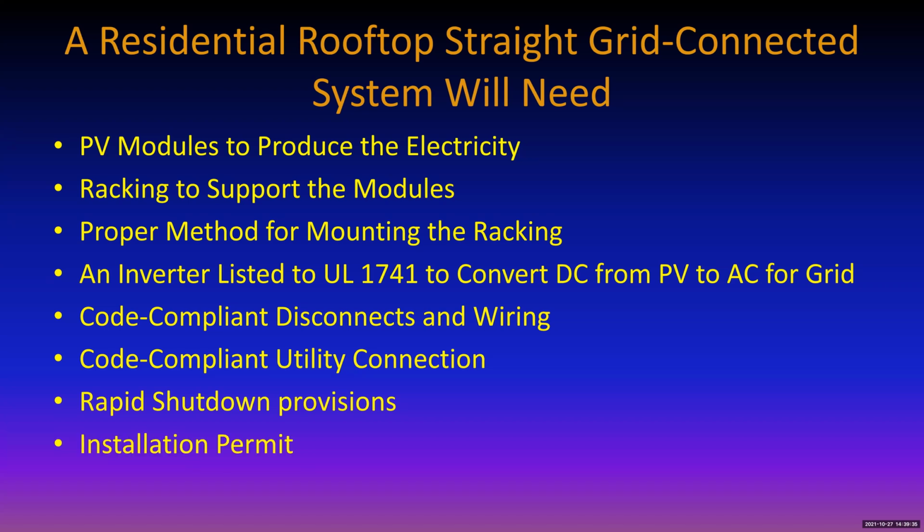Hopefully you're going to need a permit for an inspection. And you'll probably have to sign an agreement with the utility that they will allow you to export electricity to their grid, and the most important part, what they will pay you for it. Most of the agreements, as long as you don't make more electricity than you normally buy from the utility, is an arrangement called net metering, where they pay you the same as what you would pay them.